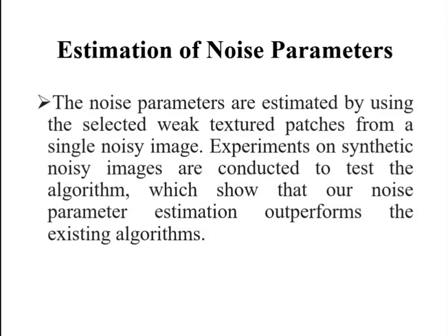Consider the image. This image is severely corrupted by sinusoidal noise of various frequencies. The Fourier transform of a pure sinusoid is a pair of conjugate impulses located at the conjugate frequencies of the sine wave. Thus, if the amplitude of the sine wave in the spatial domain is strong enough, we would expect